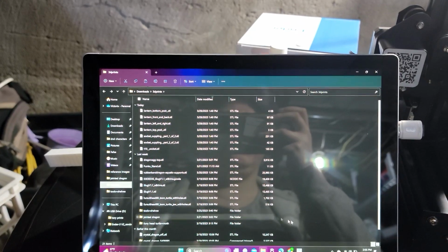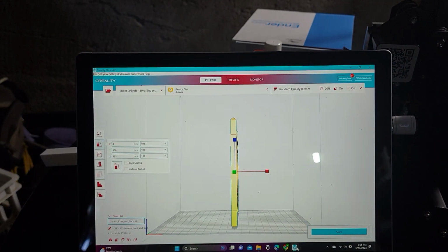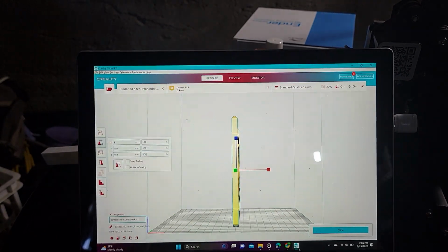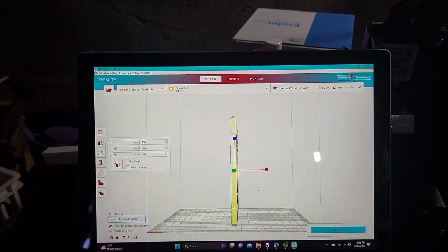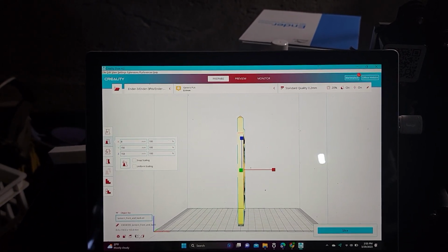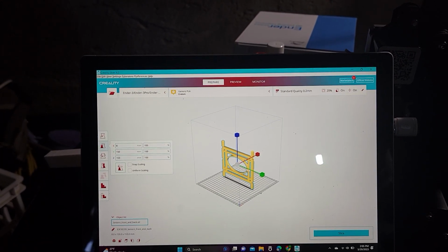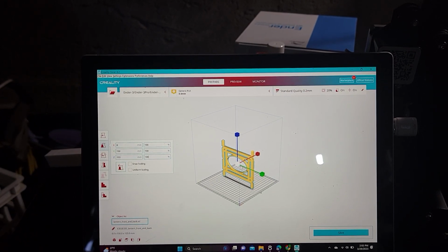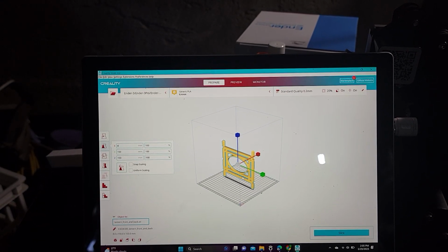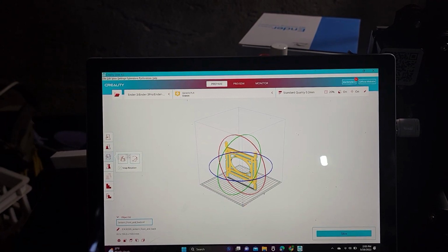So you will then want to open your slicer, which is what you will use to create the image in the file to 3D print. Oops. So it is currently up and down. I do not want this because if we change the side we view, you will notice there's a lot of open holes. And I do not want to waste a whole bunch of filament filling in those holes with supports. So I will change the orientation of the print by rotating it.